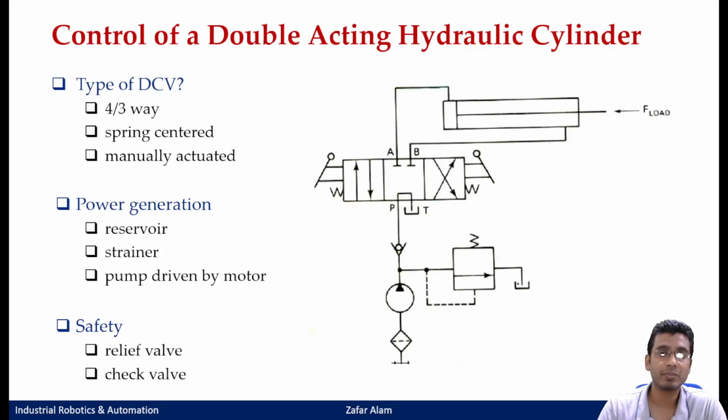Okay, so initially the cylinder is extending, that load is there, but the moment the load increases, then what would happen? If you see, this is your extension line through which your liquid extends and it is coming back from here. Okay, but say suppose if it backfires, that is the load is very much high and you did not calculate correctly what size of pump, then what would happen? The cylinder, instead of extending in this position, starts to just push back and retract, and you will have a liquid that will actually backflow through this and try to enter your pump. But if you have a check valve here, okay, then what would happen? Since this check valve allows your fluid to flow in only one direction, you will not be having any backflow of your cylinders.